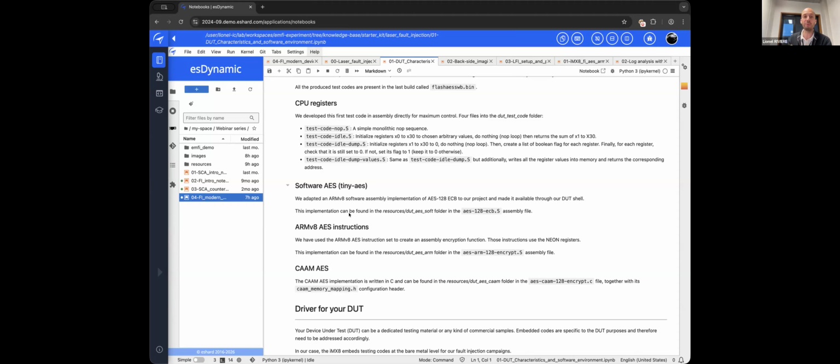If, for instance, I do very, very similar and basic code that just runs a loop of doing nothing or writing the same value into memory, and I inject a fault, I will more easily find the set of parameters that will make, or at least would have, some effect on the chip.